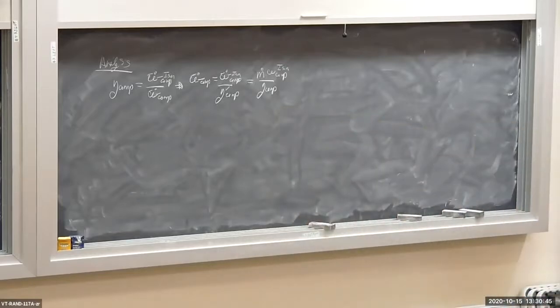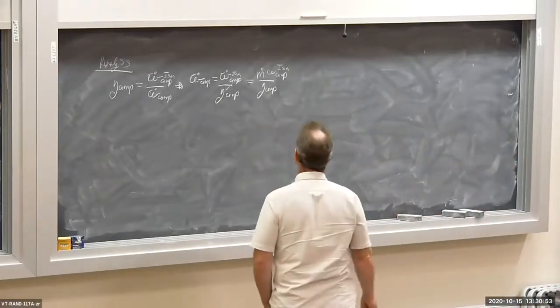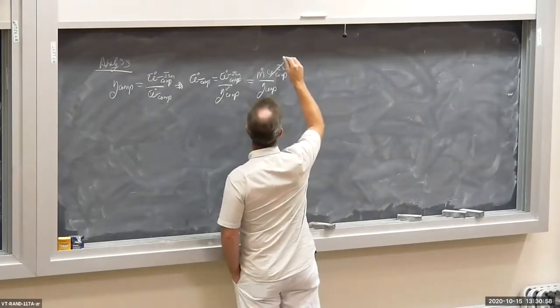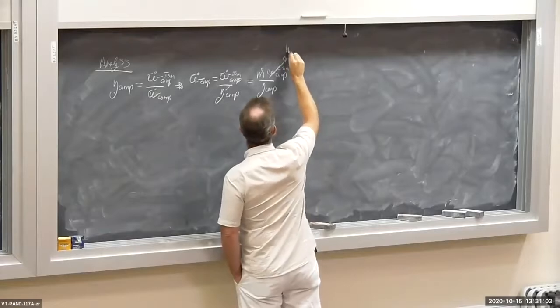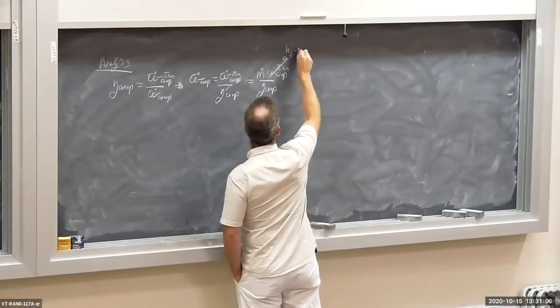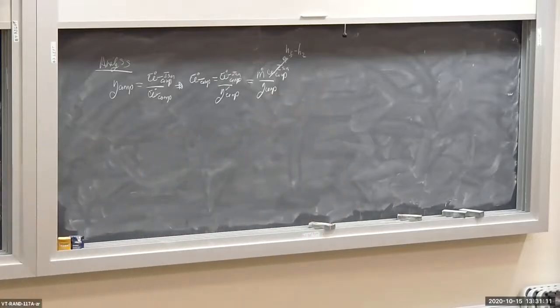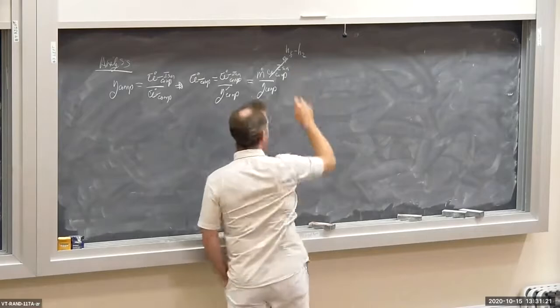Now, if I apply the energy balance for process 2 to 3s, the isentropic specific work for the isentropic compressor is going to be equal to H3s minus H2, neglecting changes in kinetic and potential energy. Now the problem is I don't know any of this stuff. I don't know H2 and I don't know H3.